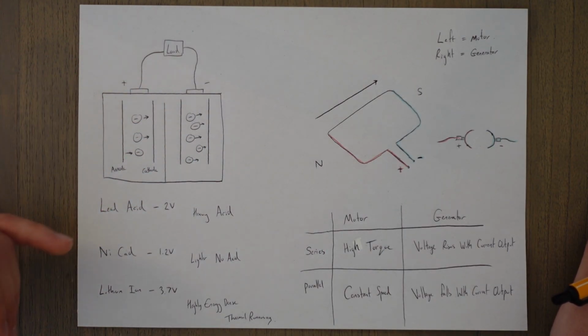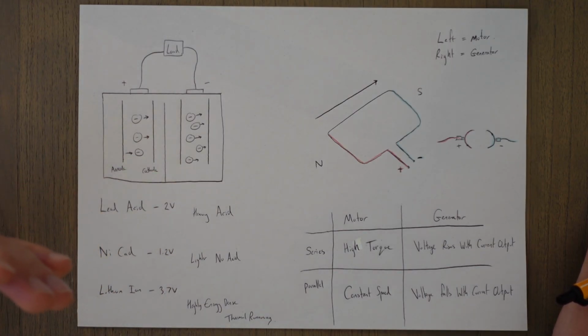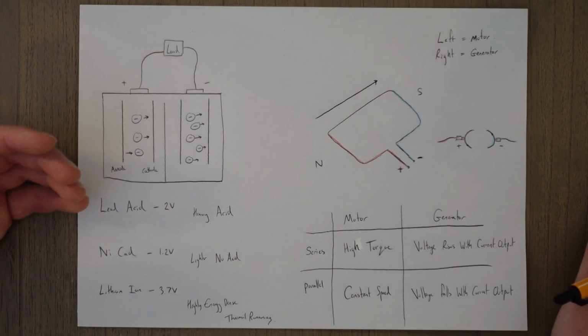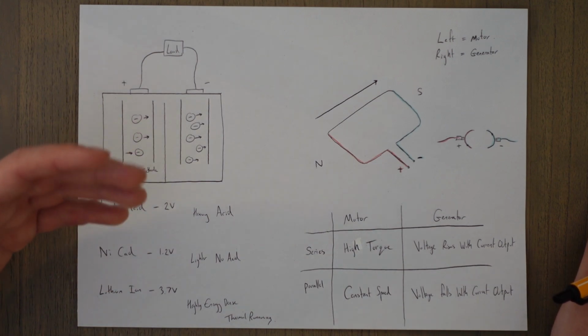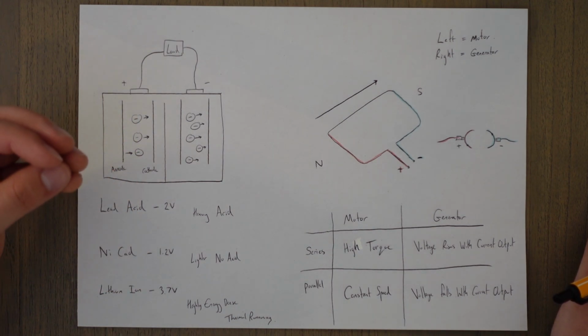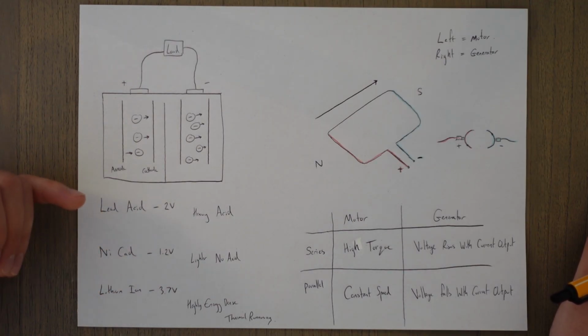So the three types are lead acid, producing per cell about 2 volts, but lead is heavy and there's highly corrosive acid on the inside, meaning that if there's leaks, that acid can corrode other components, which is not ideal. The evolution of this is a NiCad, nickel-cadmium battery. The nickel-cadmium plates are lighter, and there's also no risk of acid leaking because it's quite a gel-like material and the acid isn't as reactive, so generally a bit safer and better than lead acid.